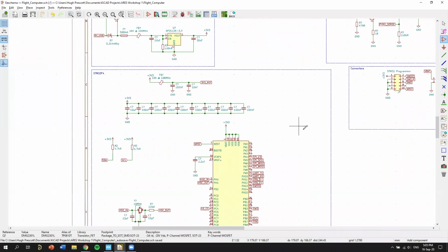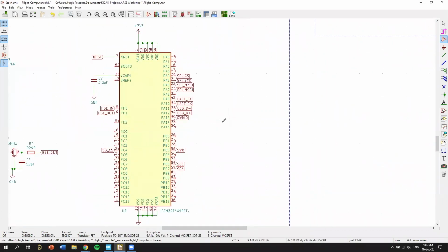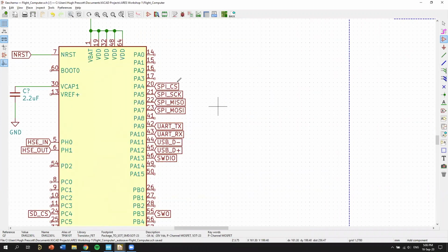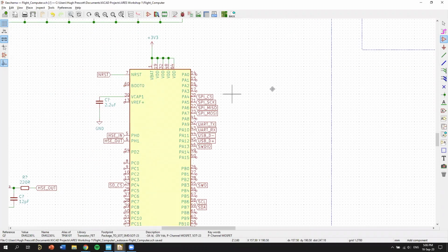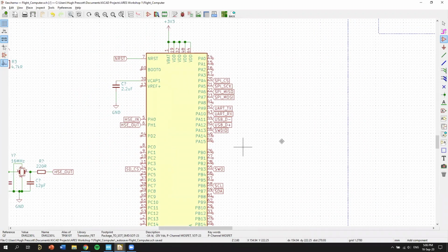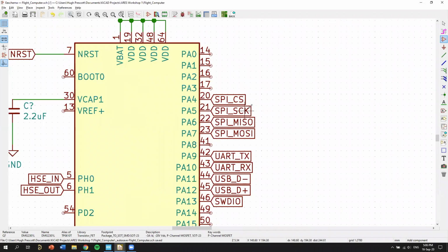Here, the way that electronics talk to each other is primarily, at the hobbyist level, 4 main protocols. One is I2C, and then we have SPI and UART, which is just your serial communication. They all have their pros and cons. SPI is the fastest, but it needs more pins, for example, and then I2C is slower, but you need fewer pins, fewer wires to connect everything.